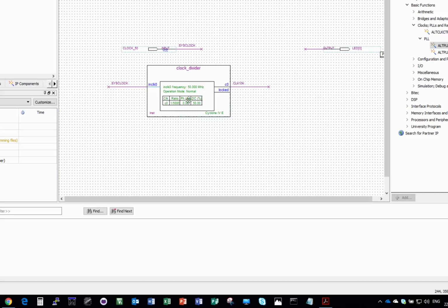So the input here and this one, I'm going to connect the LED to the locked signal. So once the phase lock loop has locked, this light should come on. If it doesn't, you know you've got a startup problem. You need to change the properties of this or clean up your clock. And now we've got a 10 kilohertz clock, we can start doing some interesting experiments and bringing signals out onto pins on relatively low grade instrumentation. So if you've got a slow oscilloscope, for example, then these are signals that most devices can cope with.